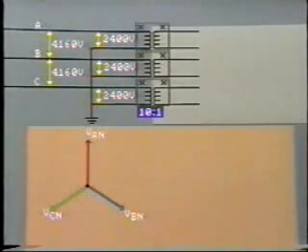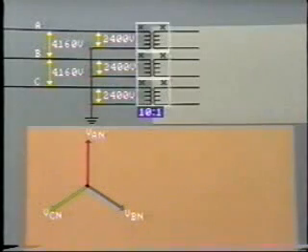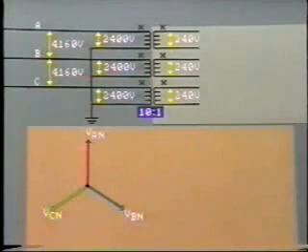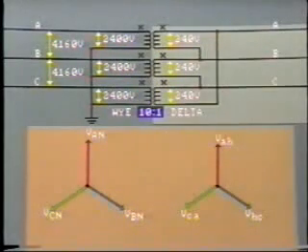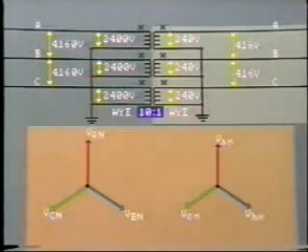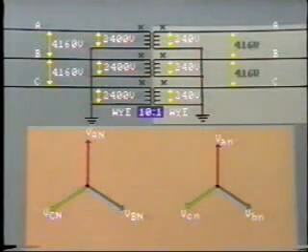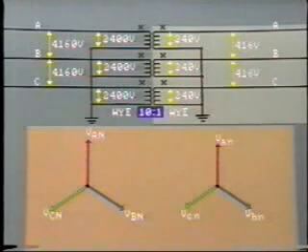Now remember, there are three separate transformers, each of 10-to-1 ratio. The voltage induced in each secondary, 240 volts, will be in phase with its respective primary. In certain cases, they may be 180 degrees out of phase, but for simplicity, we will consider the secondary voltages in phase. Now look, we have three secondary voltages available, displaced at 120-degree phase angles. They could be connected to form a delta arrangement like this, or a Y connection like this. By following the polarity markings, we now have the correct phase relationships and line-to-line voltage, 416 volts.